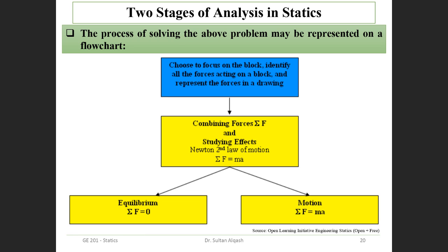Basically, the process of solving a problem in statics, as we mentioned, is that we choose to focus on a block or the bodies. We draw the free body diagram, identify all the forces acting on the block, and represent the forces in the drawing. Then we combine forces, sigma F, using Newton's law, saying there's no acceleration, so a is 0. So in equilibrium, sigma F equals 0. If there's acceleration, this is dynamics, but we will not study it here in statics.